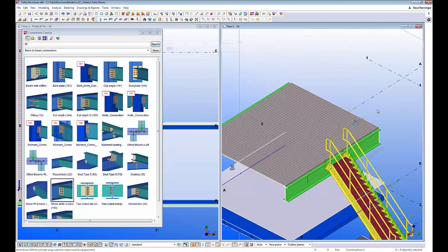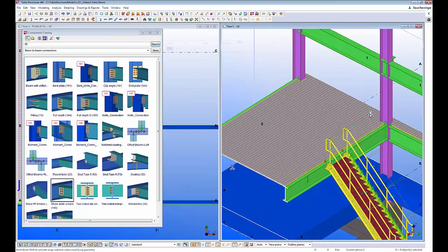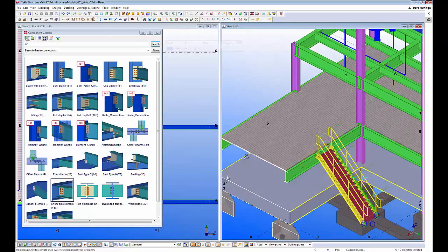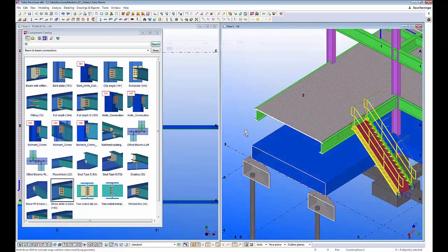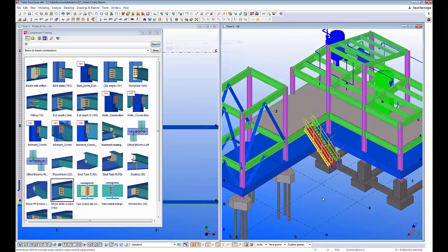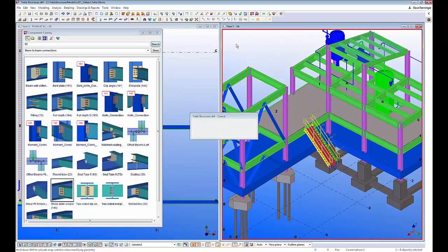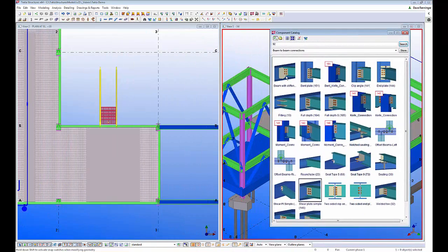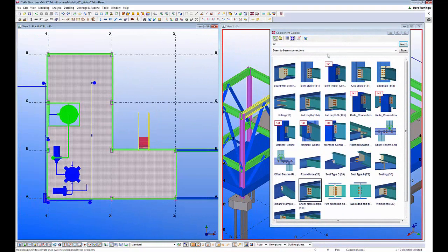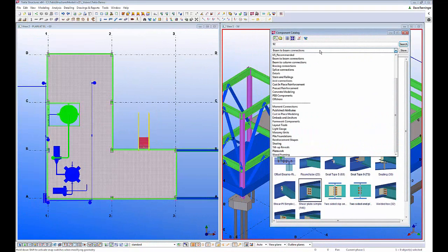So now that I have my stair in here, it's probably good to come through here. We can just remove these clip planes, simply select the scissors here and click on delete. Now we can see our entire model again. So now we have our stairs, and now let's come back over here to our plan view, and we're going to model in our rails around this platform elevation.